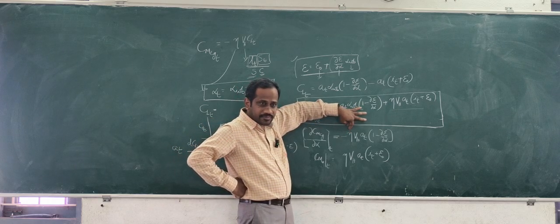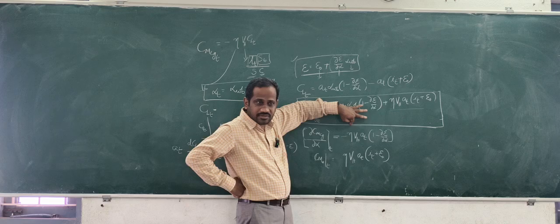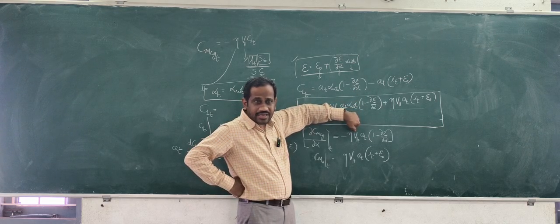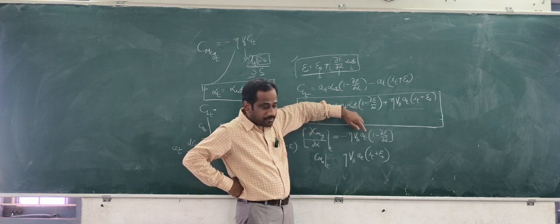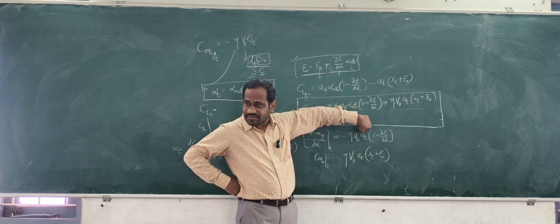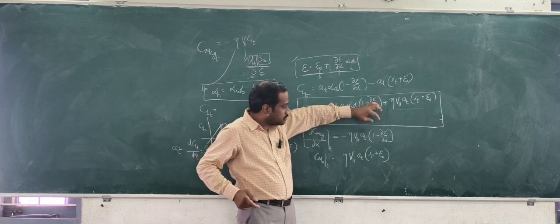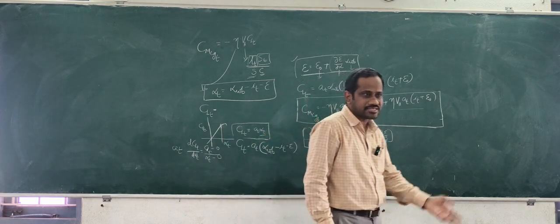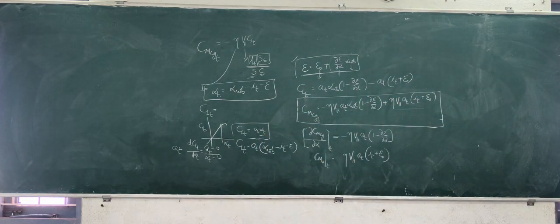This value eta, ratio of dynamic pressures, is always positive. This is the geometry property. Horizontal tail volume ratio, is it positive or negative? Positive. Slope of the lift curve of the tail is always positive. So this whole thing is positive, so no problem. Minus is not becoming plus. So it is dou CM CG by dou alpha by attaching the tail is negative. So contribution is stabilizing contribution.